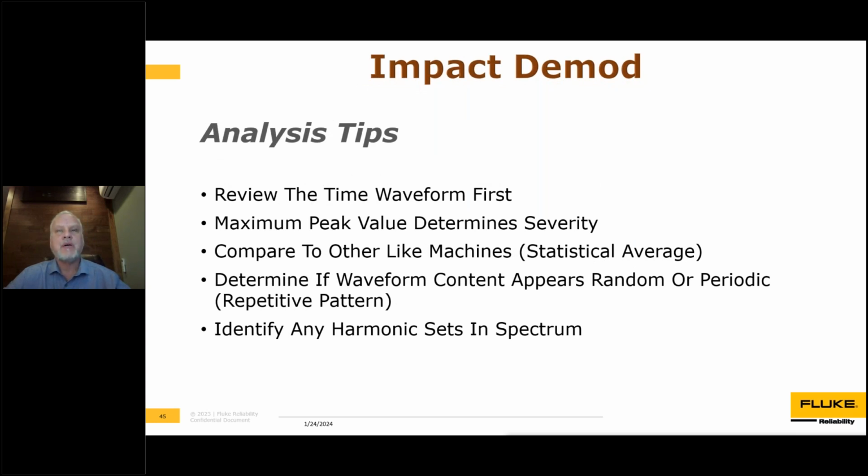Analysis tips. We review the time waveform first. This is where it turns it around for vibration analysts. Most vibration analysts are used to doing spectral analysis, looking at the spectrum first, determining frequency. This tool turns it around. You learn the severity, and a lot about the information, by looking at the time data first. So we always defer to the time data on this. Maximum peak value determines severity, and again, that's based upon relative peak value.